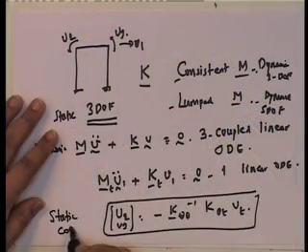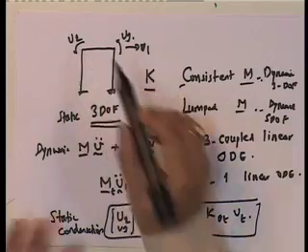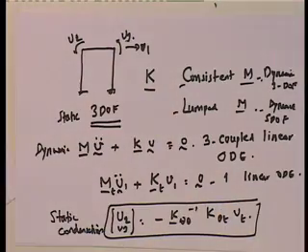In the dynamic problem, we statically condense out. This is the static condensation. If you use the lumped mass formulation, all rotational degrees of freedom are statically condensed out from the equation, and the dynamic degrees of freedom are all the translational degrees of freedom. Only the translational degrees of freedom are the dynamic degrees of freedom. So, if I have a single story building, I have only 1 dynamic degree of freedom. Even if this beam was rigid, then V2 and V3 would be 0, and it is a true single degree of freedom structure.